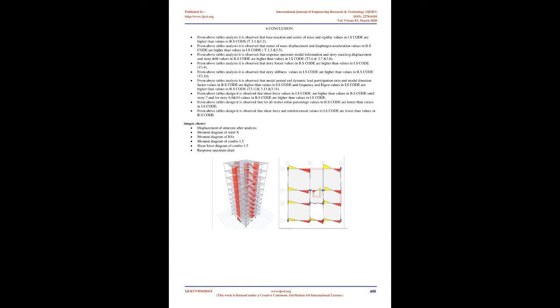A column is a vertical structural member intended to transfer a compressive load. For example, a column might transfer loads from a ceiling, floor, or roof slab or from a beam to a floor or foundations. Columns are typically constructed from materials such as stone, brick, block, concrete, timber, steel and so on, which have good compressive strength.